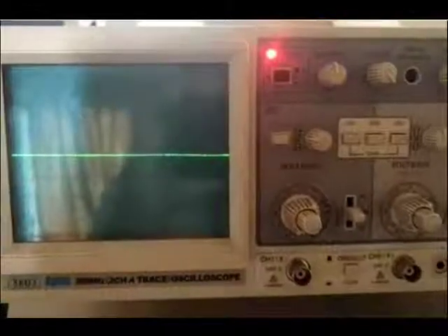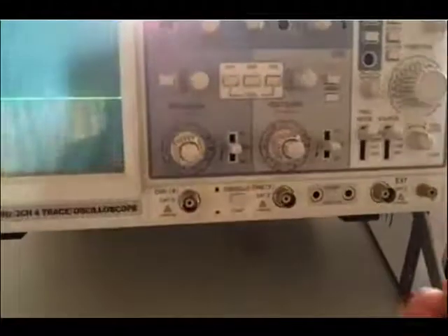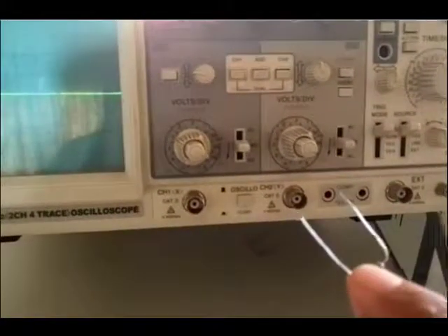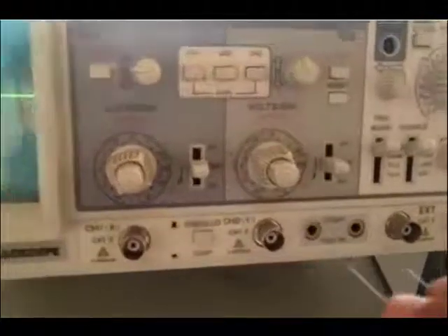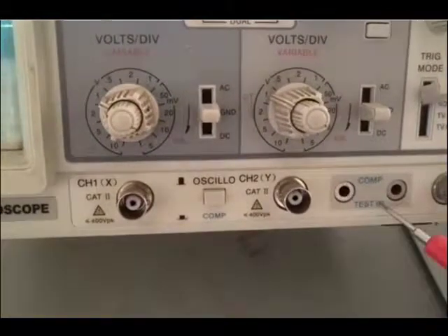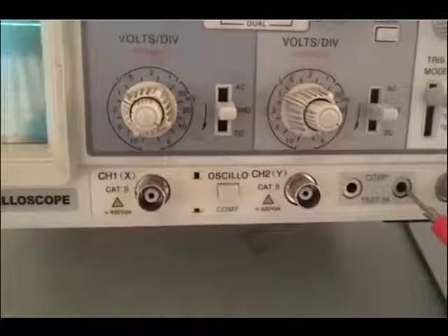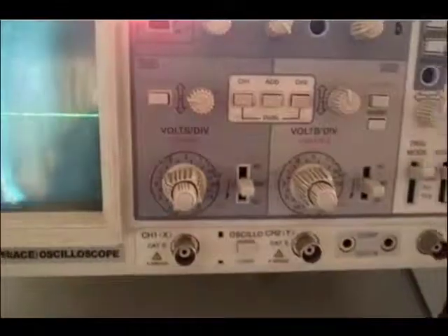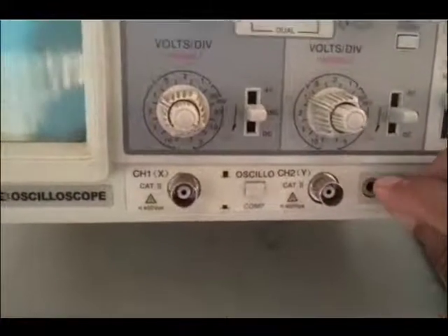I'll take as an example a simple resistor. A resistor is a two-terminal non-polar device. That means it has no polarity, plus or minus. So we can directly insert this into the component test port. They have written test in over here. So you are supposed to affix your component into this particular port. So I'll put the resistor into the port. Now the CRO displays the VI characteristic of the resistor.